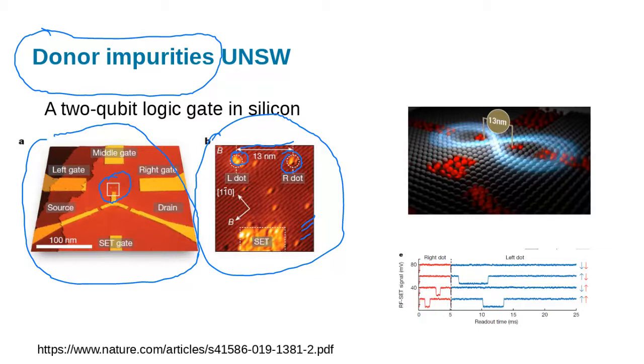So in order to have a qubit, you can't have a big load of phosphorus atoms. You need a single phosphorus atom. And so this device is a rudimentary device made based on 2 phosphorus atoms here. So these two atoms here, and these can be gated, so their interactions switched off, and this behaves as a 2-qubit logic gate. So this is something that, if scaled up, could be used as a large-scale quantum computer.